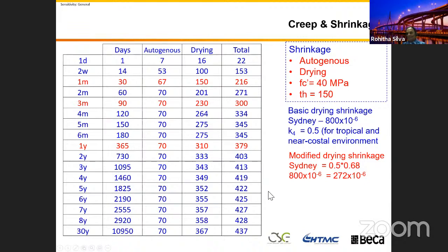Another thing I want to share with you: if you are using prestressed concrete girders and you leave them for months and months in the yard, you get girders with a significantly large pre-camber. Sometimes you will have a real problem getting your bridge alignment right on site. You need to be really mindful. Later on, we will do some calculations to understand this in a better way. These are the things that matter when you play with creep and shrinkage, especially the prestressed concrete girder cambers.